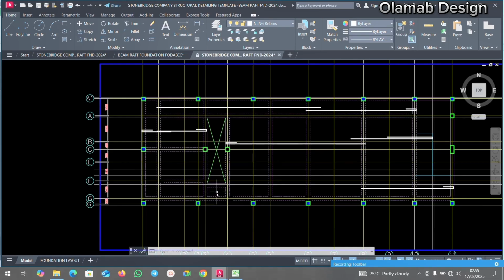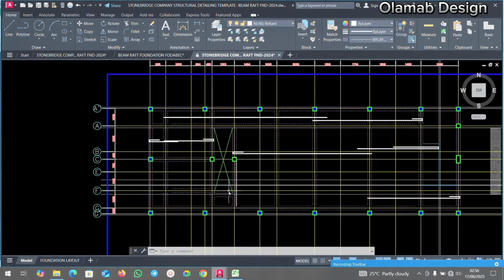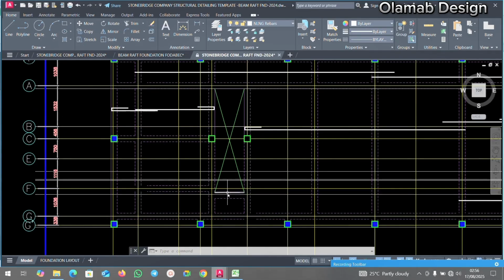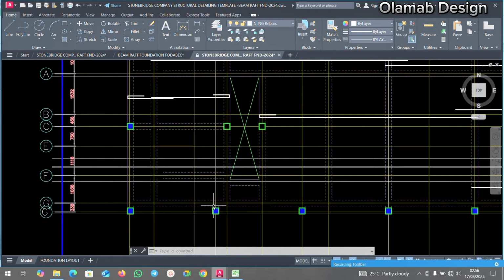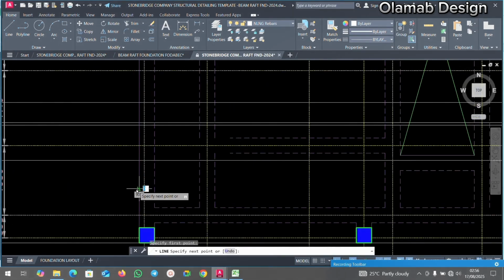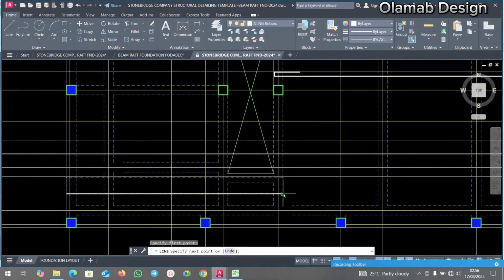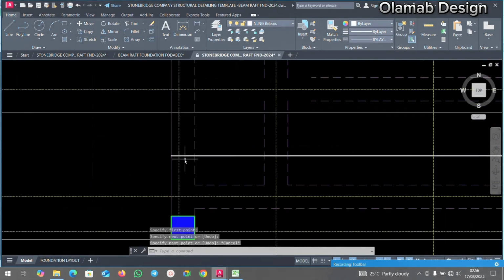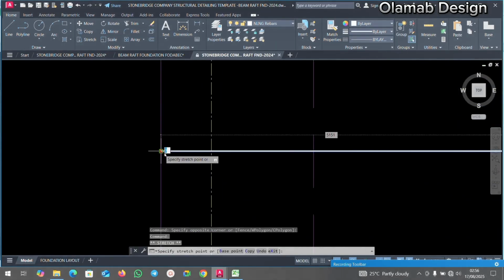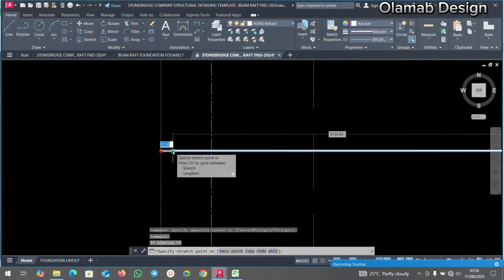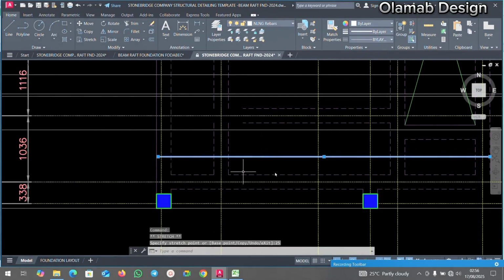If we have a straight bar, you can choose to leave this one. It is expected that the person on site is also an engineer. So when it gets to this point, it should know that this reinforcement is going to run from here straight down, and when it gets to this point, it's not going to have a return. So you can choose to have your straight bar at this point. Then you have your return here. You take this one inside by 25, you hit enter.